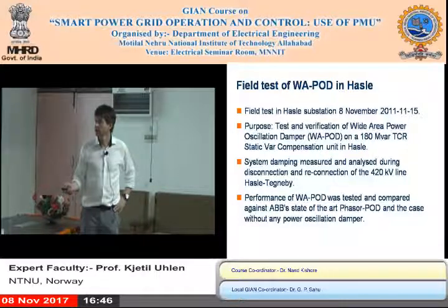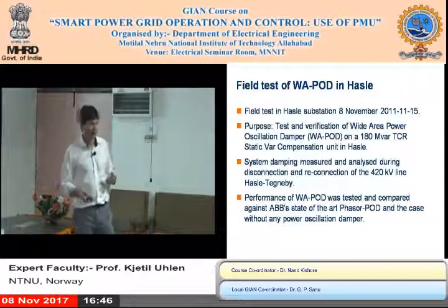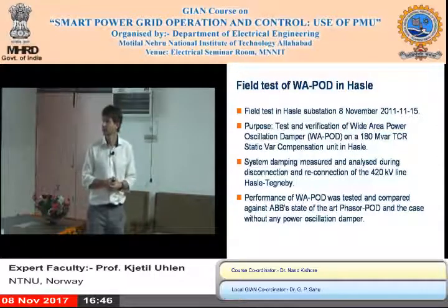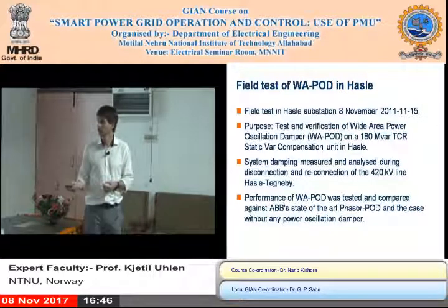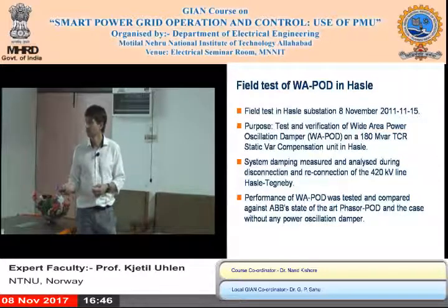We excited the system by disconnecting and reconnecting lines close to the site, and we tested and compared the performance against the conventional, state-of-the-art power oscillation damper that ABB manufactured, and without any POD.